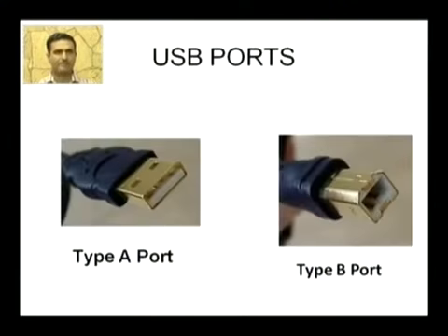In USB there is serial communication, as its name tells, Universal Serial Bus. For the USB there are 2 ports. These are the USB type A port and USB type B port. Type A ports are simple, their shape is rectangular, and they are generally used for low bandwidth intensive devices. Type B ports are square in shape and generally used